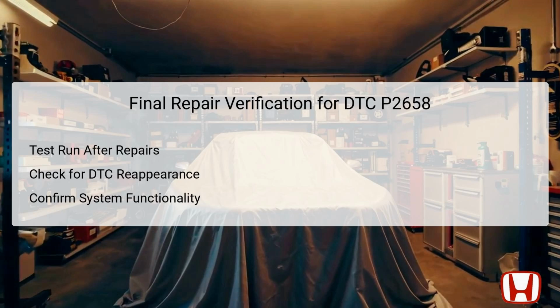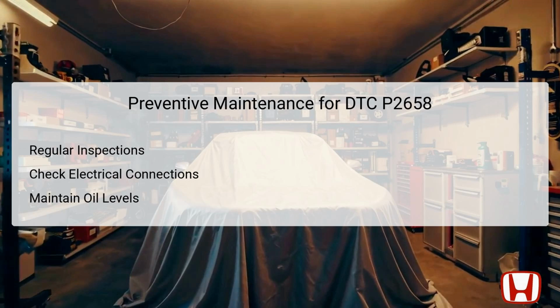This verification emphasizes the importance of not only repairing the fault, but also guaranteeing that the vehicle meets emission standards and operates efficiently. Preventive maintenance is essential in avoiding issues like DTC P2658 from recurring. Regular inspections of the rocker arm oil control solenoid A and associated wiring can help to identify potential wear and tear before they lead to performance problems.